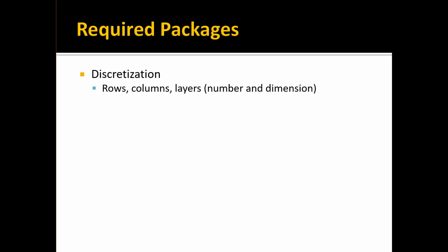So now let's talk about packages. There are a set of packages which are required, meaning you always have to use them. One of them is the discretization package. This is part of the global process. It's where you define your rows, columns, and layers.